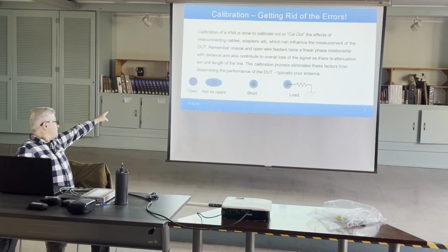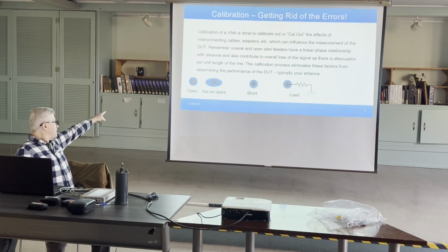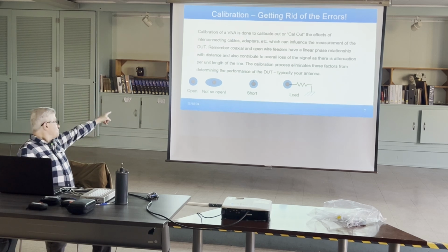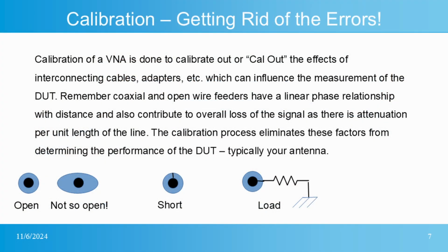What happens to the impedance of the cable if you do that, right? What happens to it? It changes, right? Because it's dependent on the outer diameter of the inner conductor and the inner diameter of the outer conductor, and then the dielectric material that the cable is made out of. That's what determines the impedance. So if you can't determine what that outer diameter is, because it's now an ellipse instead of a circle, it's kind of hard to know what the impedance is.